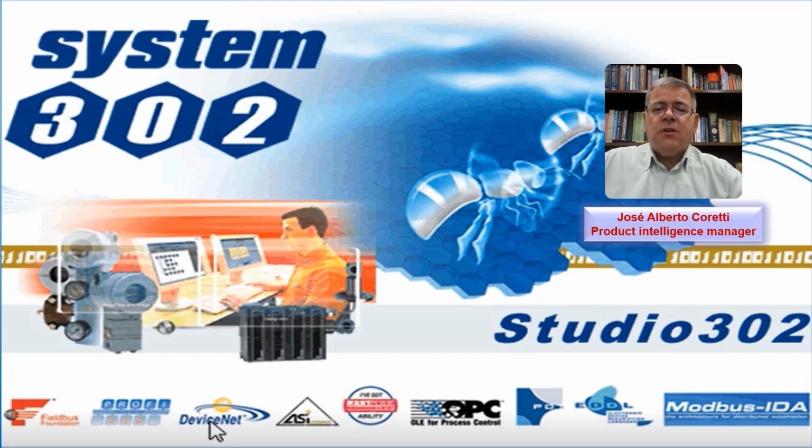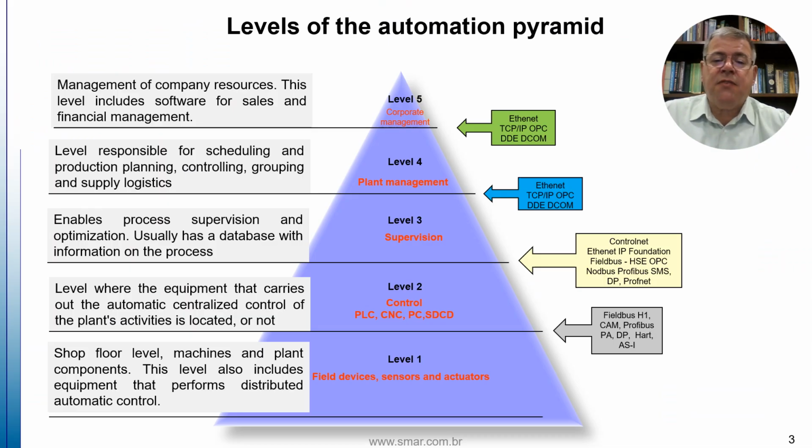In this video we will discuss Foundation Fieldbus technology. This slide shows the famous automation pyramid. Field level is level 1, where we find digital networks, especially the Fieldbus. Level 2 includes controllers, SDCDs, PLCs, and PCs, CNC tech. Thus, the Foundation Fieldbus system exists as an intermediate component positioned between Level 1 and Level 2.